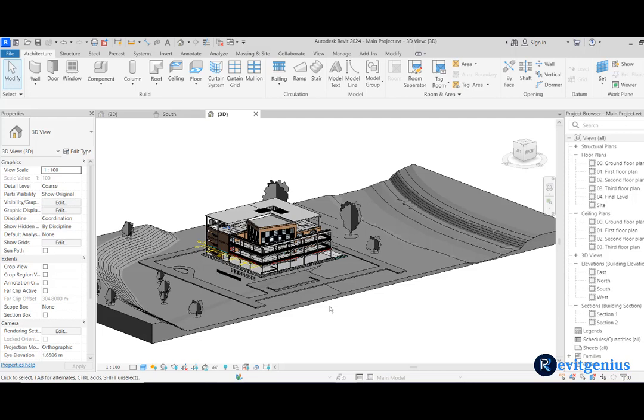The topography will be replaced with a Toposolid. You can now layer the Toposolid, assign materials to it, and edit it using the tools that were introduced in the previous section. The regions that were deleted using the delete instance command can be redrawn using the subdivide tool.